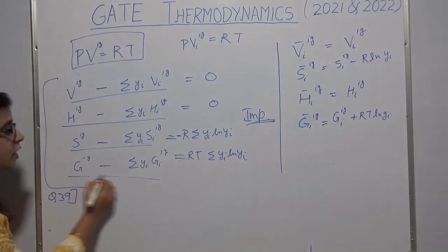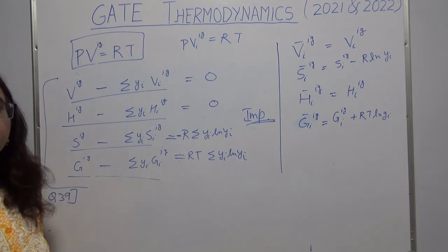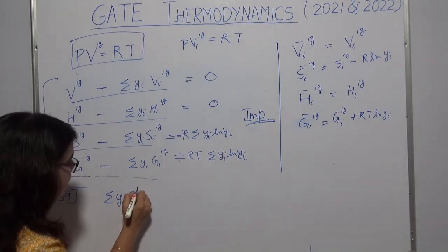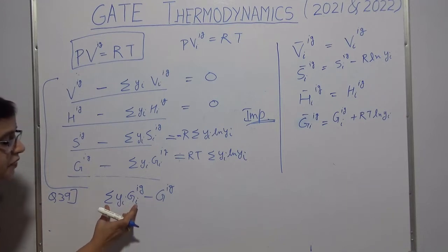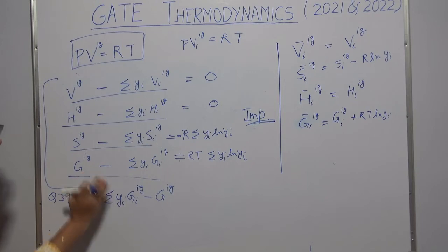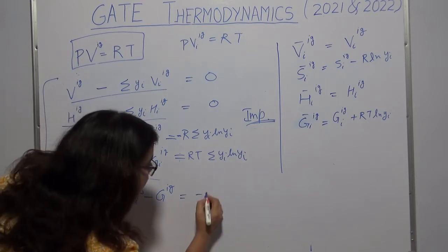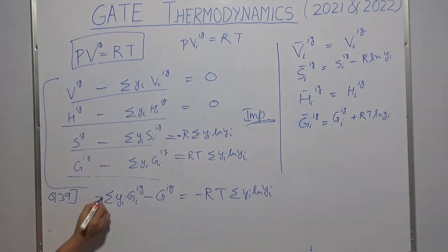We have an equation for the Gibbs energy change of mixing. If I want to separate this mixture, then I am going opposite. Instead of forming the mixture, I am trying to separate it. So these are the species which are separated now, and this is the mixture. I have to find the difference, and now it will be the reverse of this equation, because here I am mixing, here I am separating. So this minus this gives the equation for the minimum work required for separation, and this much work you will have to do in order to separate that mixture.